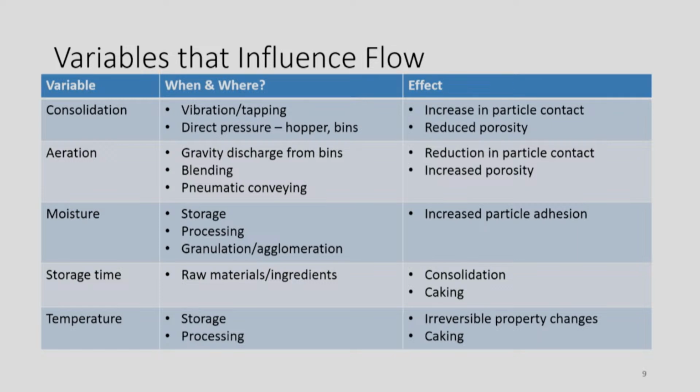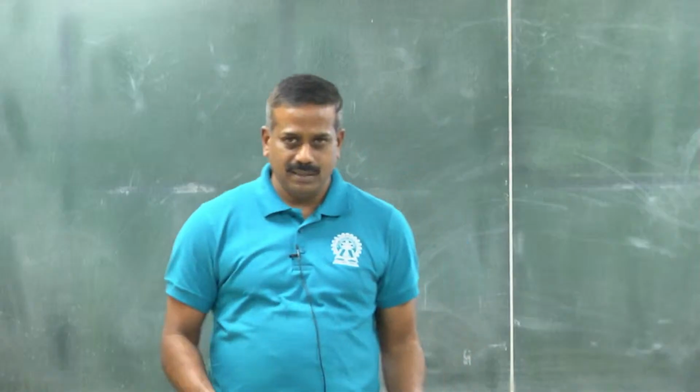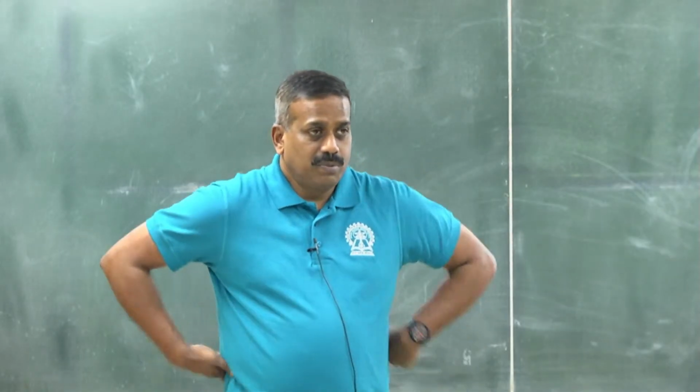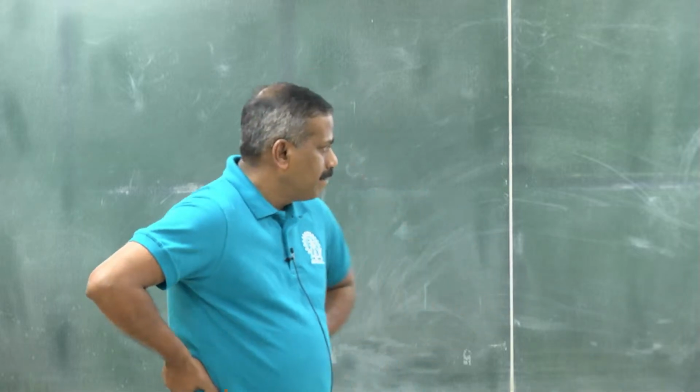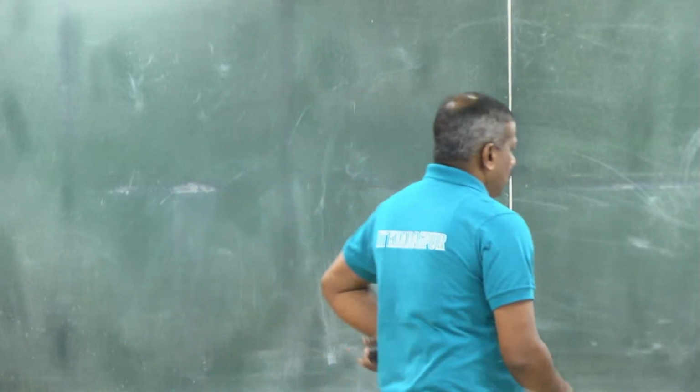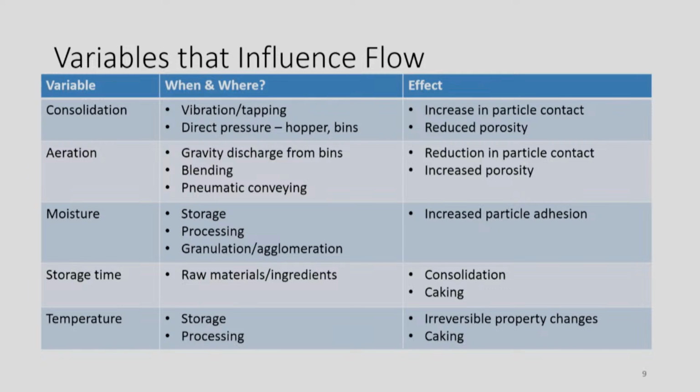Right? So has any of you measured glass transition temperature? You all know about glass transition, right? Again, for agriculture students, you might not know. Glass transition temperature is the temperature at which the property changes, from a glassy state to a rubbery state. Their molecular vibration level changes. That leads to property changes in powders. It leads to caking or other effects. Again, that will also affect their flow and handling properties.